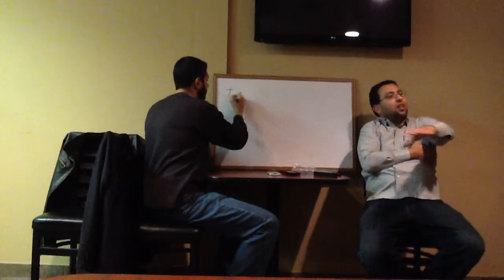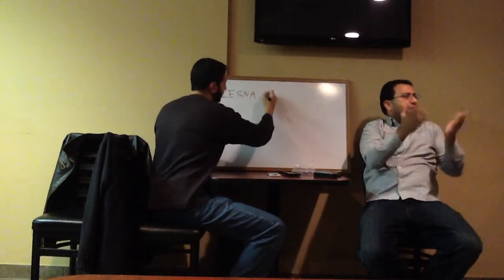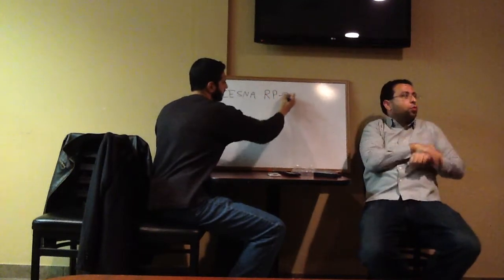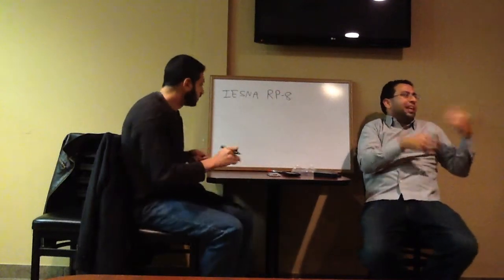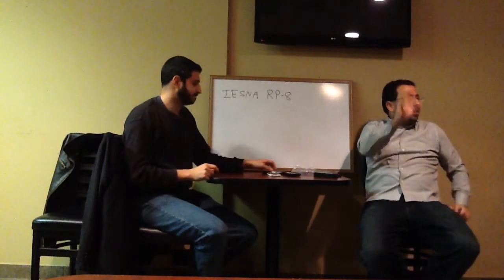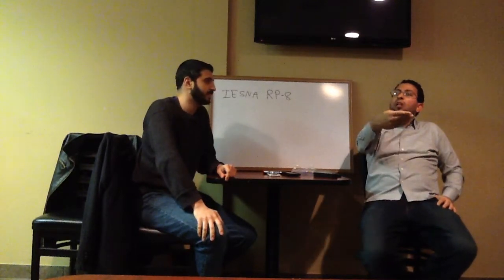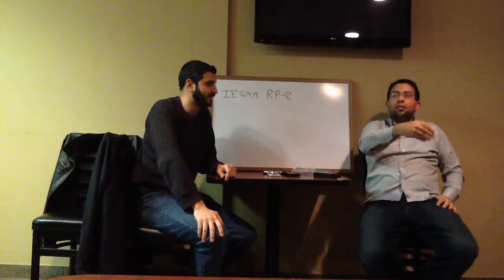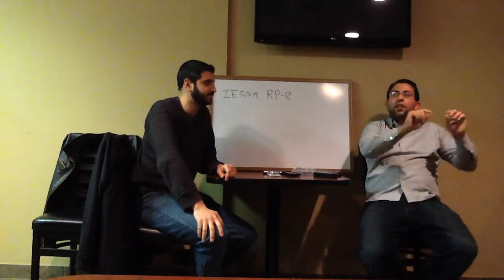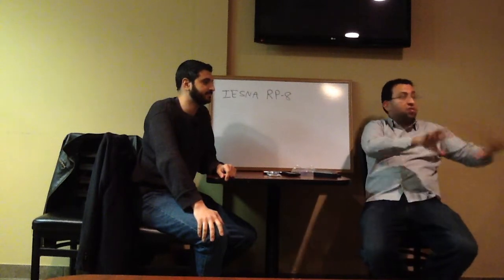Basically, what are we talking about, guys? We want to do a design for a roadway. You need to know what kind of roadway it is. If it's a major, it's by code. You have to go to a book called RP8. It's a code by the government. It tells you the foot candle levels, and it's a street guideline, so you have to follow it. You have to maintain certain foot candles. It's like a table: you go back to it, find out what kind of street you are designing for, and match whatever they have.